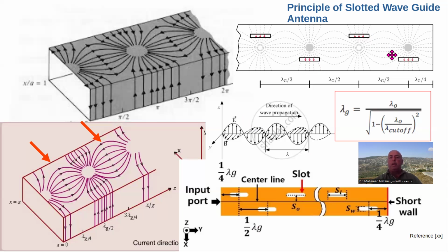Now, right now, you can see that the spacing from the center of these slots is equal, and that's what we call uniform distribution illumination. This is like in signal processing, like a pulse. If you take a pulse and FFT it, you're going to get basically a sin x over x with the side lobes at 13 dB below.